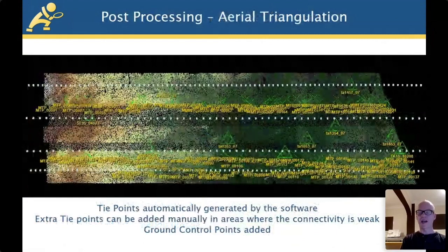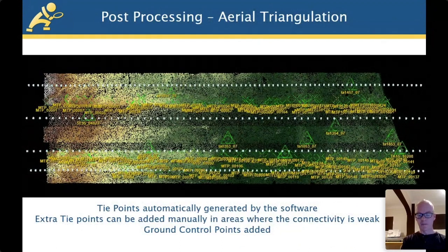Now, to position and accuracy, the second part of our positional accuracy is aerial triangulation. So again, this is further refining the measurements of the relative position of every individual photograph relative to every other one. So the inputs are our position, with the GPS position and the roll, pitch, yaw.